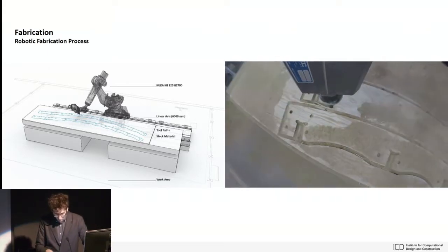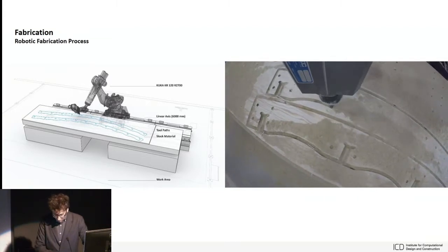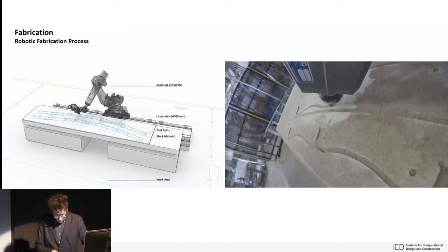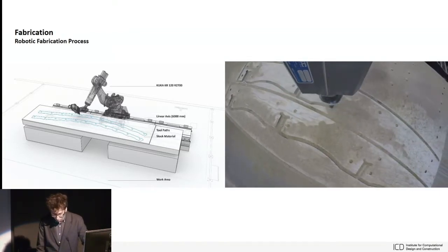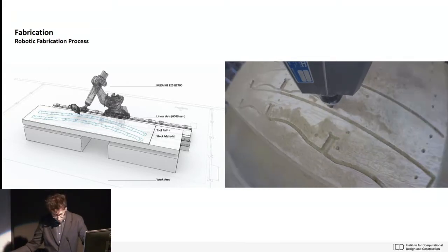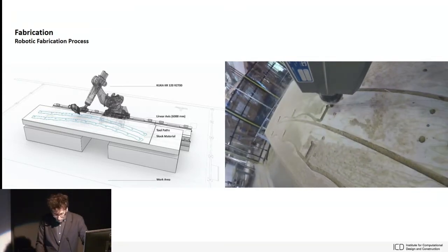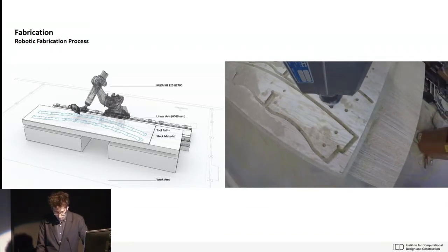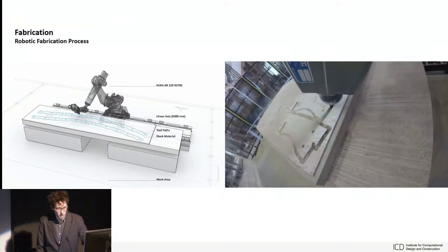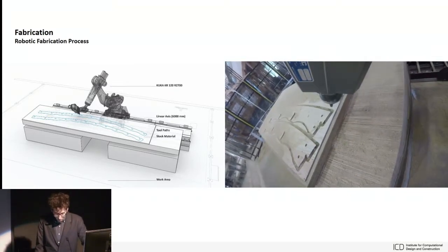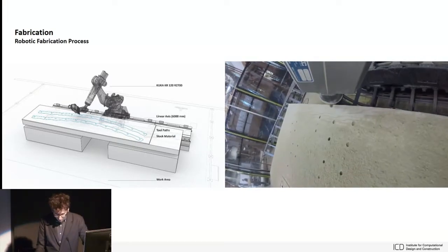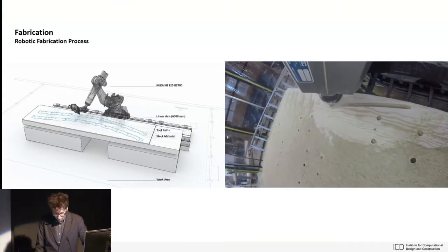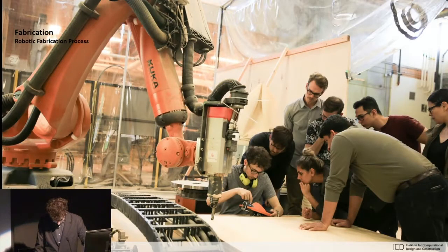So we had in this case also some kind of automated design fabrication process that would basically export the fabrication data directly, and we use the robot here simply because of the large workspace. Again, it's a more or less normal milling process, of course very individualized, very automated in this case. All these elements have a different shape, but the fabrication code is automatically generated. And we simply use this large, in this case 6 meter long, linear axis. It gives the robot such a large workspace compared to normal CNC machines.